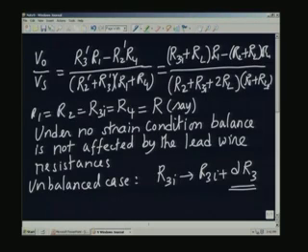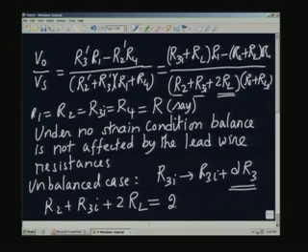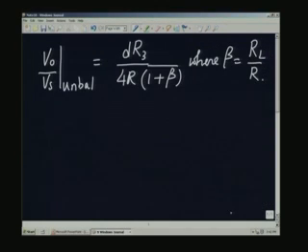You have R 2 plus R 3, plus 2 R L, and R 2 equal to R 3 I. So, this becomes 2 R. I am taking the factor 2 outside, R also. So, R 2 plus R 3 I plus 2 R L is nothing but 2 R plus 2 R L, which is nothing but 2 R into 1 plus R L by R. This 2 R into 1 plus R L by R, I am calling it 1 plus beta, and that is what I wrote down in the next page.